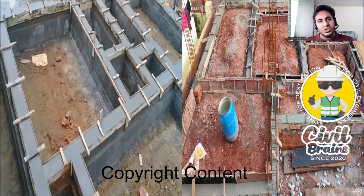But on this side, you see here, this length is not completely going, isn't it? Why? Because your shuttering is only from here to here, and again from here to here. That means in the middle portion, is there any shuttering being done? No, it is an open area, so that your secondary beam will connect here. So when you find this length, you take the overall length, and whatever is the width of this particular beam, you need to deduct, and then you find the shuttering quantity. Getting my point? So I hope this is understood.